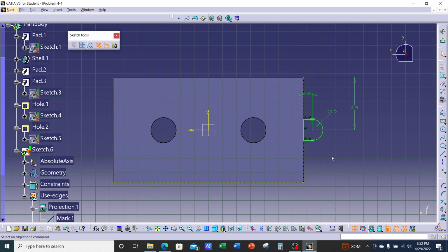Okay, so this one we can actually mirror. So I'm going to select. I'm going to left mouse click and hold from the opposite direction and select my sketch or my tab, as you can see, or you can select one at a time while holding onto the control key, and we're going to mirror it over. So here's mirror. Okay, so mirror. I'm going to mirror it about the vertical. There it is. Click in space to deselect.